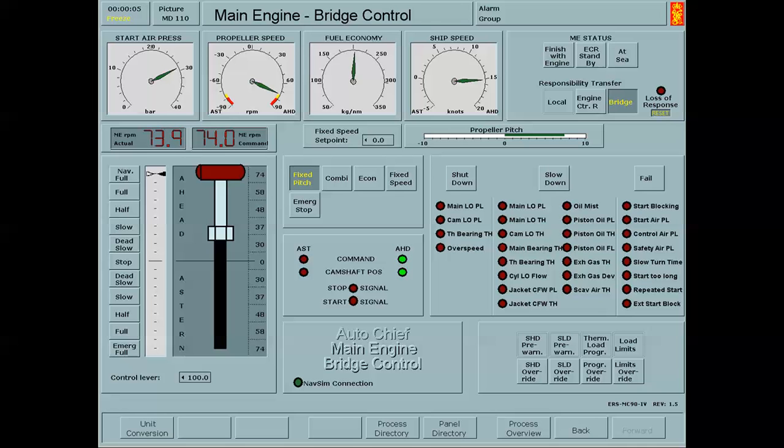But specifically, when you get into a storm, when you have heavy winds, it is very common that you have to slow the main engine down. Now this used to be done manually by the engineers. They would be looking at their load indicator, which is just your rack setting. The rack setting is how much fuel oil is being delivered into the engine from the high pressure pump.